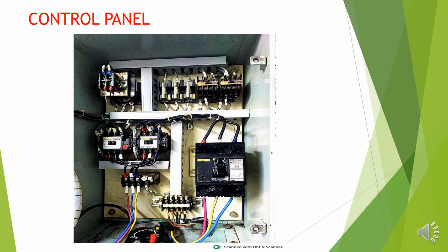So the 88R interlock is 51 and 52, so this is normally closed, and below that there is the 13 and 14 normally open contact. Okay, so one more thing, you know that once this contactor 88F energizes, at the same time 88FX will be energized, and that 88FX is this contactor. This is called the auxiliary contactor.